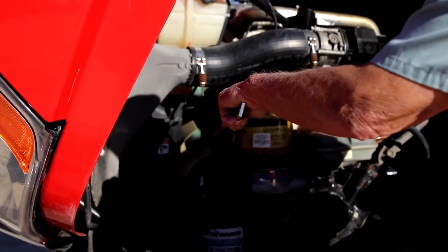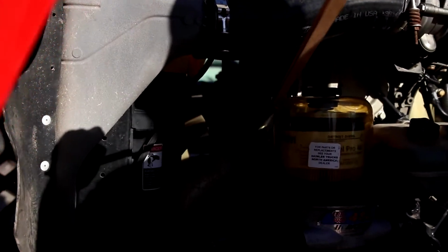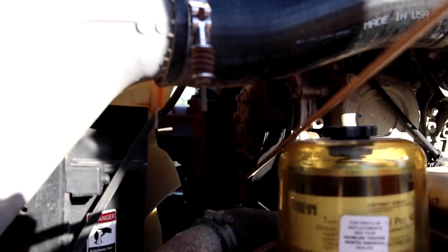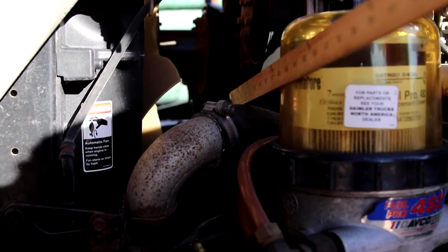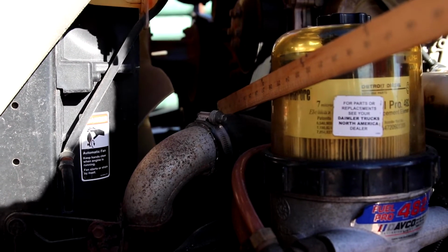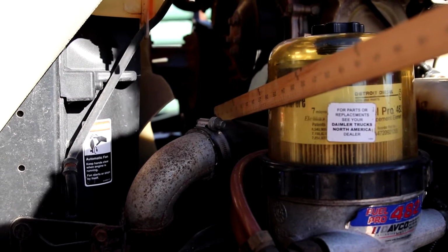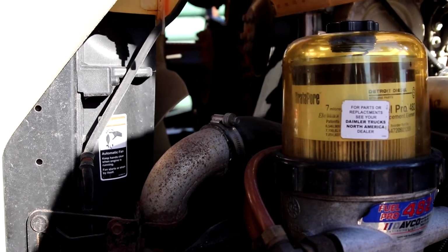Dropping down, you have your fan belts running again, so check on this side too to make sure your fan belts are fine. This is another radiator hose. You want to check that. Held in place with clamps, no abrasion, bulges, and cuts, no leaks.